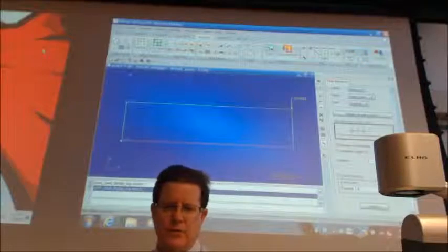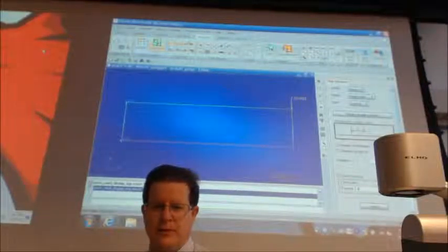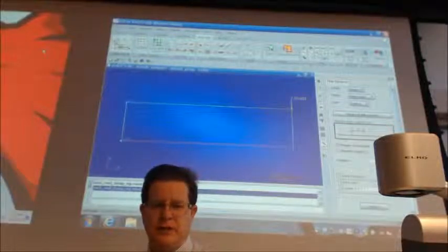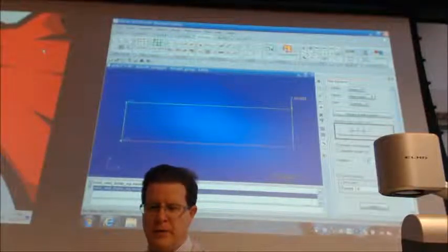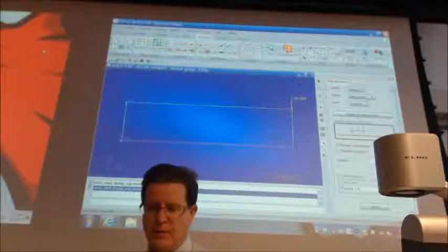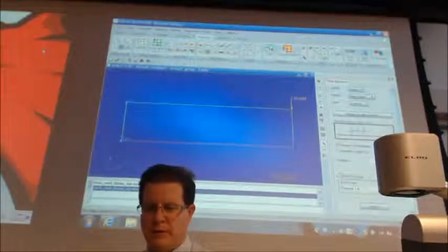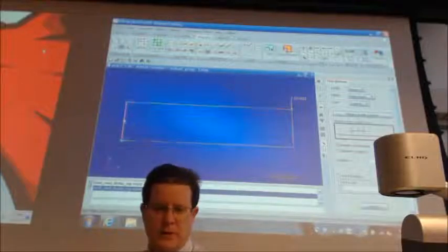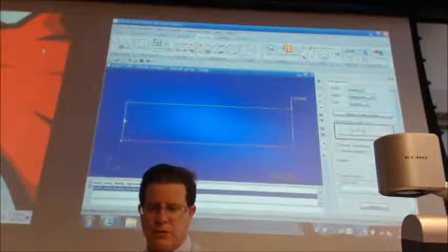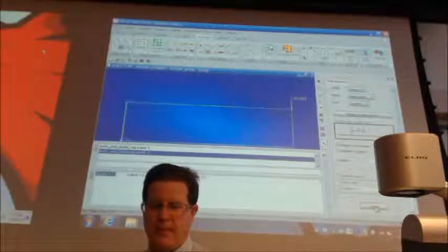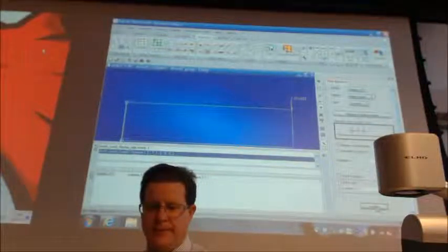Okay, so now for meshing, you're going to do mesh seeds, uniform, number of elements. We want to set that to 1, and turn off auto execute. And we're going to select this edge. So it's surface 1.1. Hit apply.